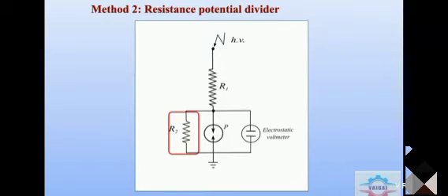With sudden changes in voltage, such as switching operations, flashover of test objects or source, and short circuits, flashover or damage may occur to the divider elements due to the stray capacitance across the elements and the ground capacitance.